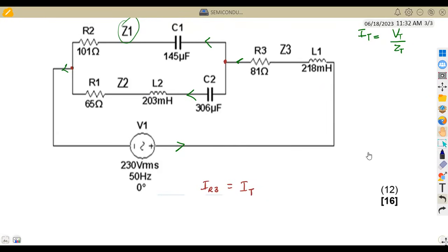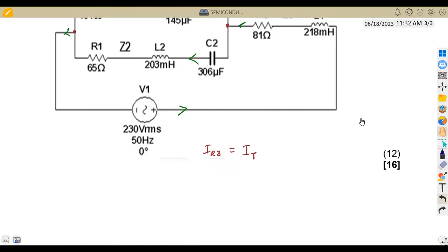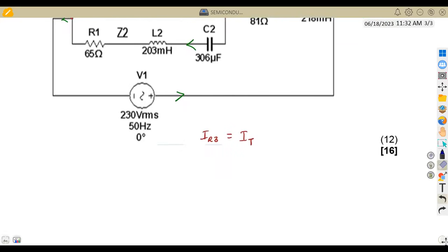So on an RLC circuit, what you need to do is to compare. What you need is to compare between the XL and the XC that you're going to have, because our Z2 can be given as R plus jXL minus XC, like this, provided that our XL in this case is greater than XC.